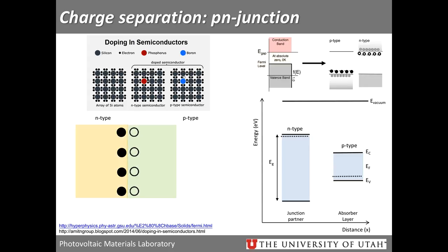When those are brought together, first, when a PN junction is brought together, you have just a huge concentration gradient. The N side has a huge concentration of electrons. The P-type has a huge concentration of holes, so you get simply some diffusion problem. Electrons want to flow from N-type into P-type, and holes want to flow from P-type into N-type. Does that make sense? What those leave behind is fixed point charges. Where you've added extra free carrier holes and electrons before diffusion, after diffusion, you leave those atoms behind that are in a charged state. So does that make sense?